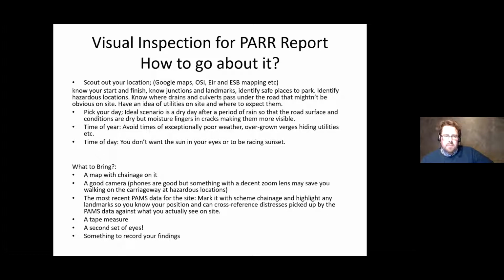Just simple practical things as well. Pick your day. So your ideal scenario is a dry day, so your surfaces, your conditions are dry, but not long after a period of rain so that the moisture is still in the cracks. It just makes them that bit easier to see, especially things like hairline fractures and surface cracking. It's so much easier if there's a bit of moisture lingering.